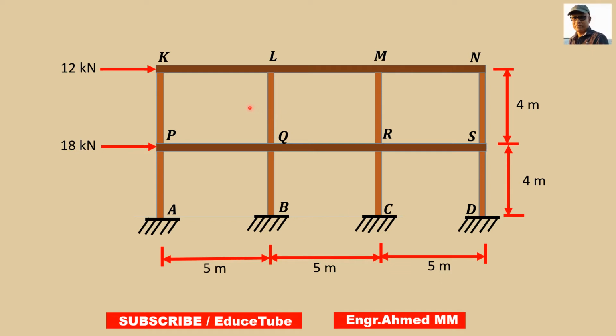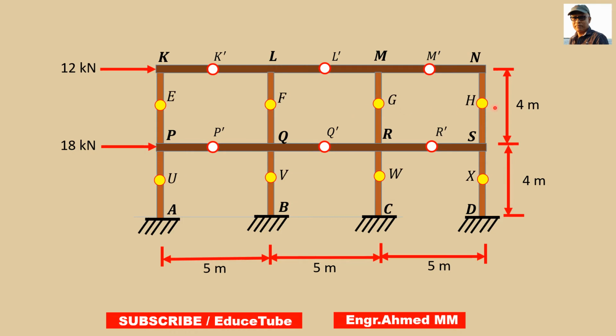First assumption, a hinge is placed at the center of each girder. We can see it here. And these hinges are assumed to be a point of zero moment. Second assumption, a hinge is placed at the center of each column, and here this hinge is also assumed to be a point of zero moment.